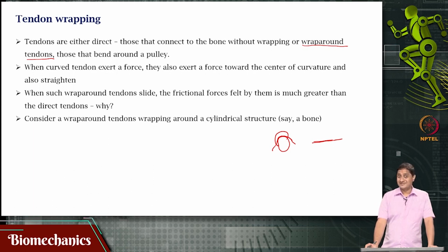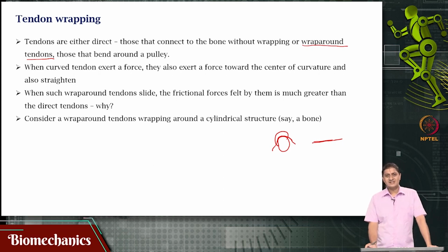We will have to check why this is the case, because one likely reason is that the contact area increases. But you would say that contact area does not affect simple friction mechanisms such as Coulomb friction. But actually this is not true. In many cases, contact area has a very important role in deciding the amount of friction and resistance. Maybe the coefficient of friction might not change, but the amount of force that is felt will be affected by the contact area.